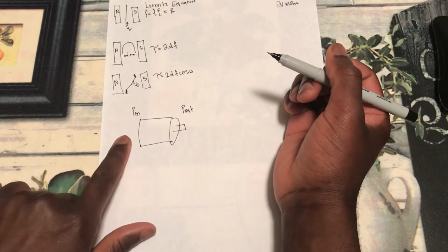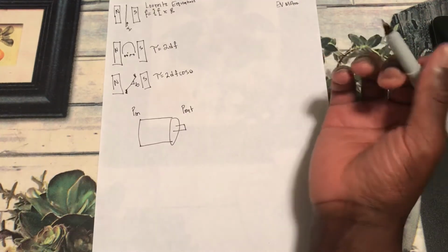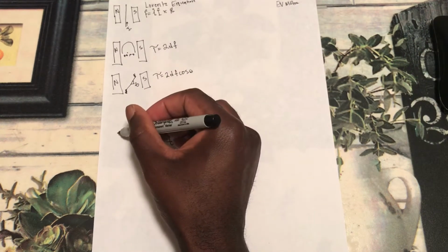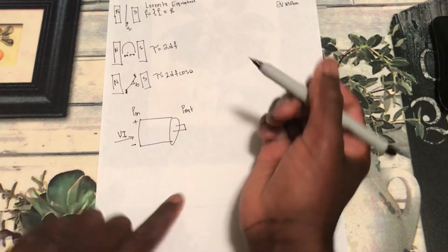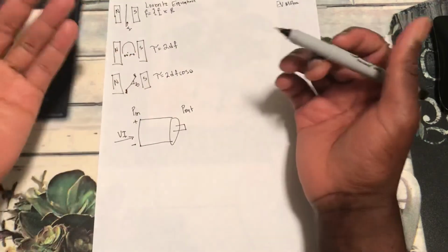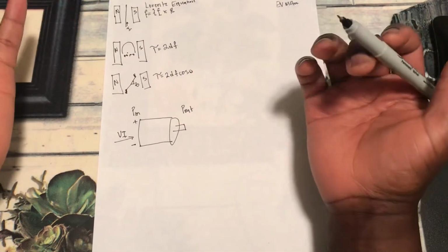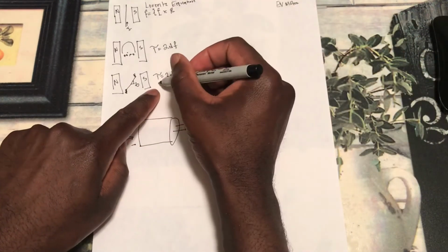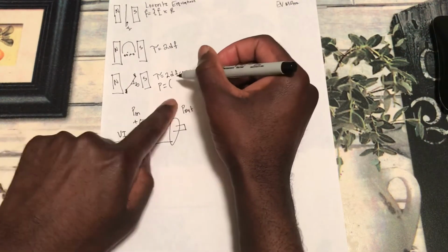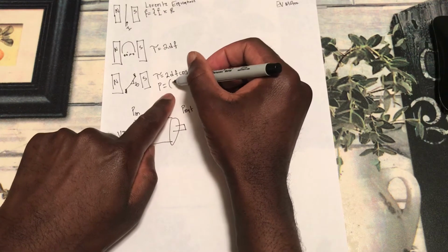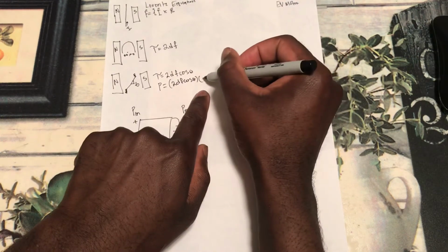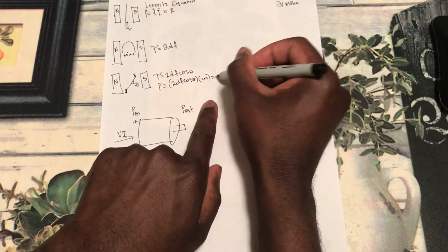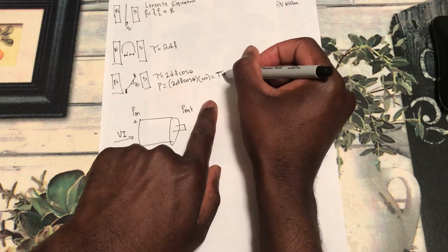And we know that the power that's going to go in is simply just the electrical power, and that's just the voltage and the current. But what will come out now, there will be several things that will come out. And one of those things will be power to do mechanical work. From this equation, we know that power here is equal to the torque, which is 2dF cosine theta, multiplied by omega, which is the angular velocity. And we can write it like so for space.